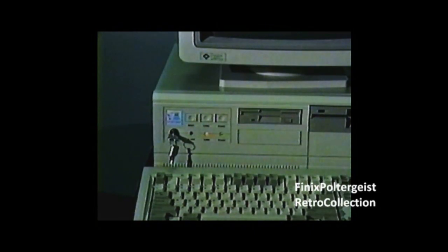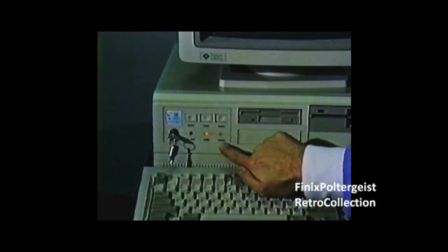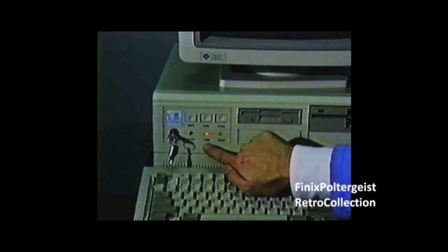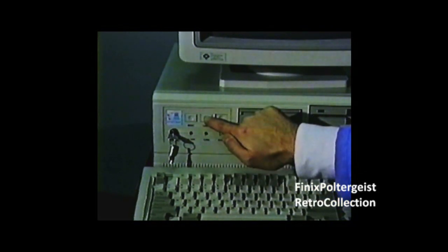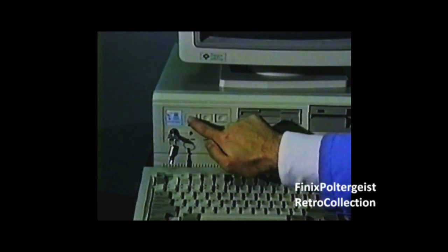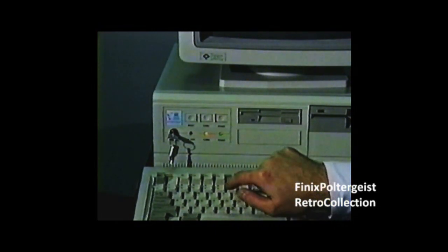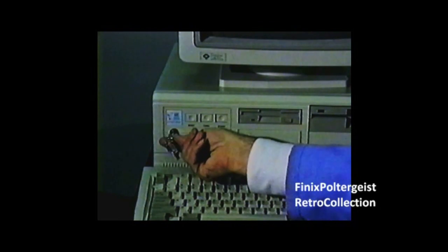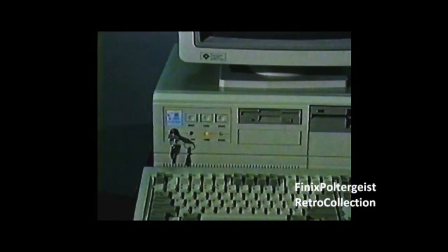Check the operation of the controls on the front of the case to make sure their connections are working. The power light should be on when the system is switched on. The turbo light should be on when the turbo is engaged. The reset button should reboot the machine. When the lock is engaged, the keyboard should not be able to input to the computer. On this particular machine, the fastest speed of the system is 33 megahertz with the turbo switched on and 8 megahertz with the turbo off. Your machine is now ready for testing.